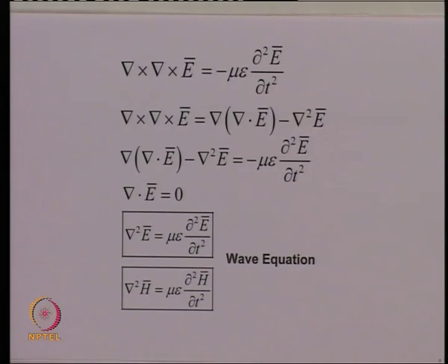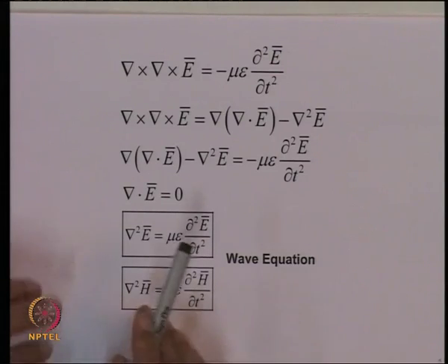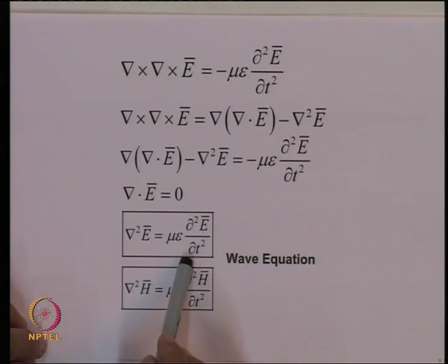So, now to find out the behavior of the electric and magnetic fields inside the optical fiber, essentially we have to solve the wave equation for the electric field or for the magnetic field, and once you get any of these quantities, then we can go to Maxwell's equations, substitute into them and find out the other quantity.